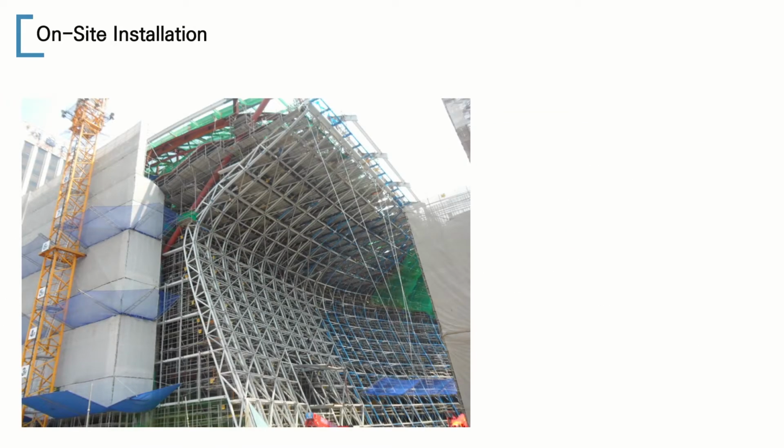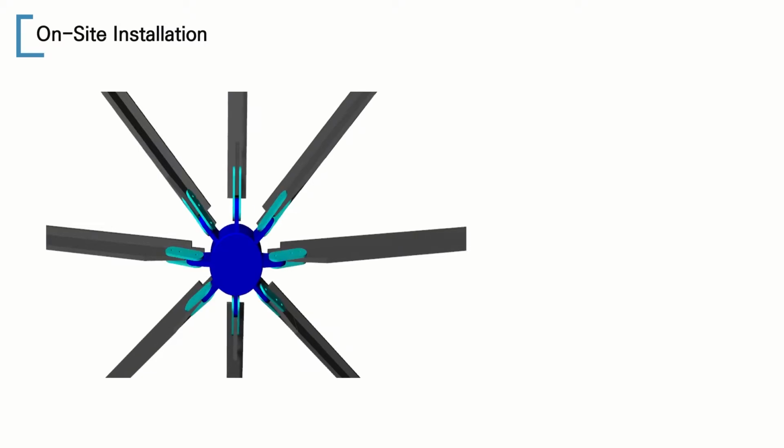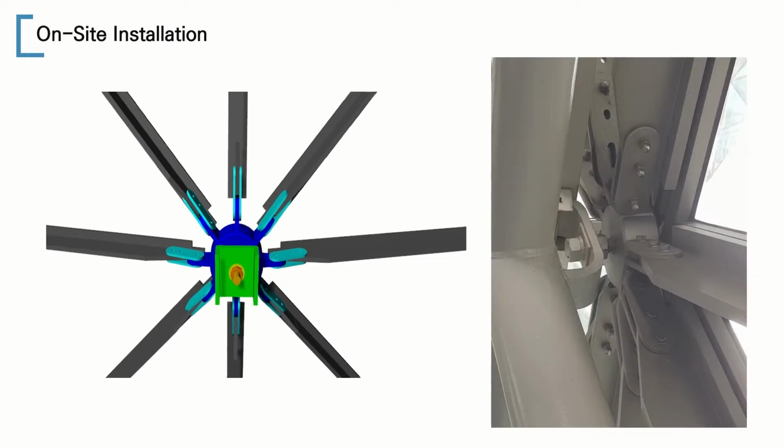And this time, let's take a look at the process of assembling the glass. First, a nonlinear 3-dimensional curtain wall frame should be installed for glazing. The installation sequence is: first, align the T-bar to the shape, connect it to the anchor with a clip, and finally bolt it to the previously installed steel frame, like this.